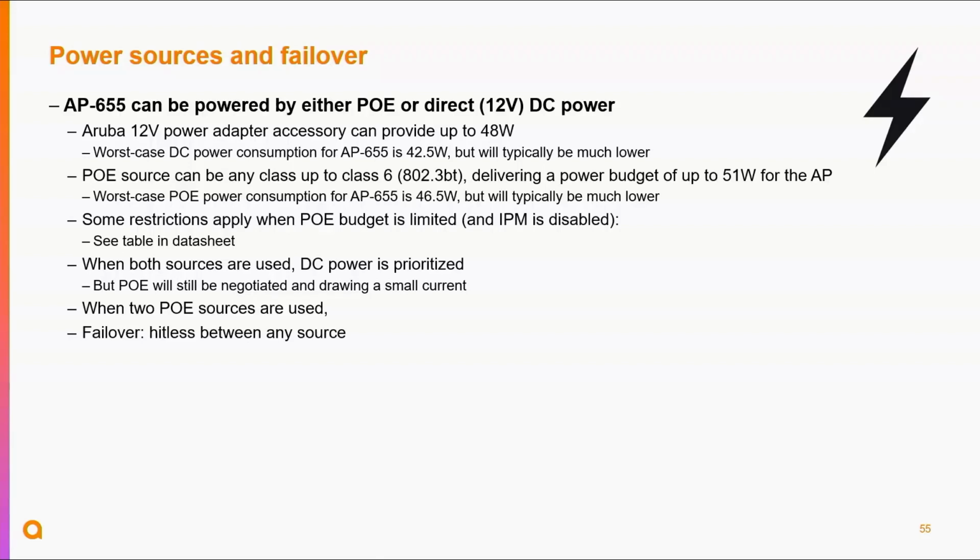DC voltage is 12. Since we support both voltages, the first thing we need to do on the PoE side is convert it down to 12 volt. And then from 12 volt onwards, we go to a dozen, 15, 20 different voltages and different sources to supply power to each and every single component on the board.